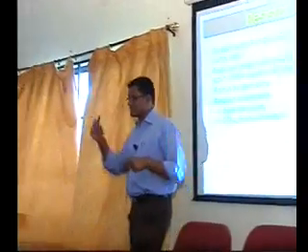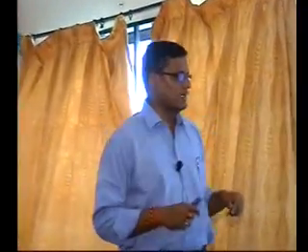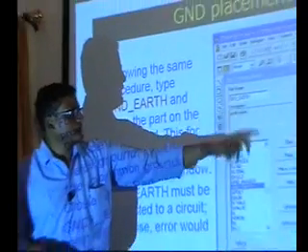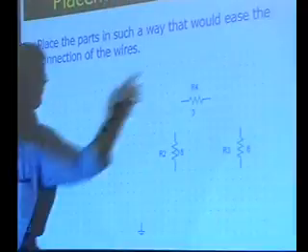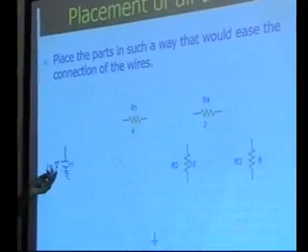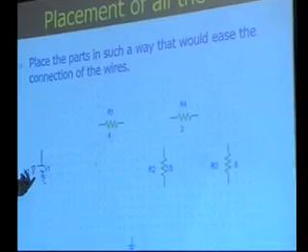Resistors and all we can place. Next slide. So we are placing the ground. I am selecting the ground and placing it. Next. So I have placed my ground and a couple of components, including the voltage source. This voltage is, say, around 12 volts.